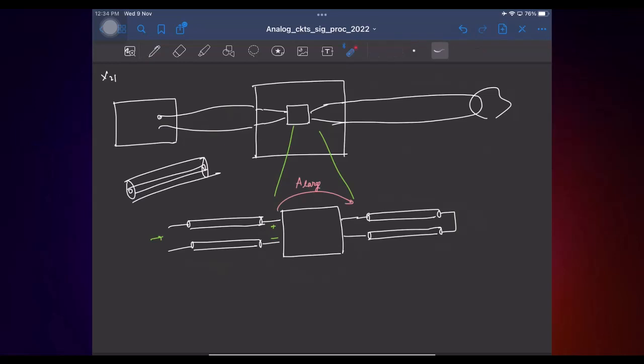So that wave goes here, gets reflected back, but some portion of it will also get leaked to the input, right? I mean, an amplifier ideally is supposed to conduct or transmit signal from the input to the output, but in practice, due to the parasitic capacitors, you'll also have a finite leakage into port 1. So we'll have a small alpha getting coupled there.